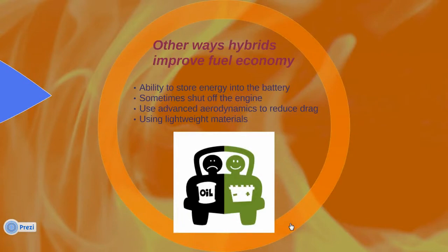And there are also other ways hybrids can improve fuel economy. First of all, it has the ability to store energy in the battery. Whenever you step on the brake pedal in your car, you are removing energy from the car. The faster a car is going, the more kinetic energy it has. A hybrid car can capture some kinetic energy when braking and store it in the battery to use later. Secondly, sometimes it can shut off the engine. It does not need to rely on the gasoline engine all the time because it has an alternate power source, the electric motor and batteries.